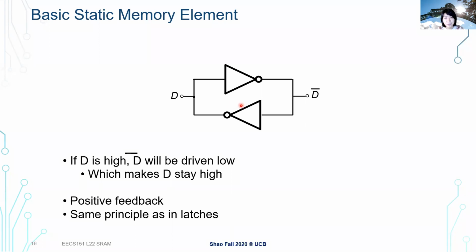You may be wondering, earlier I said a 6T SRAM style structure is very commonly used, but now you're only showing us 2 inverters. Each inverter is 2 transistors, and we spent a lot of time talking about inverters a month ago. So now there are only 4 transistors. What do the other 2 transistors do? That's a really good question.